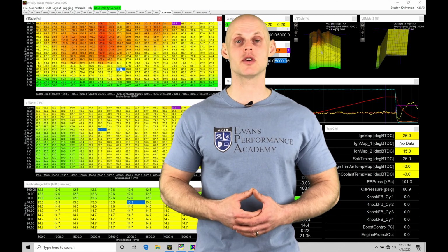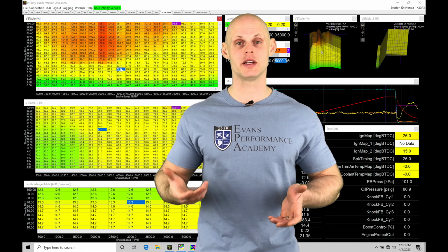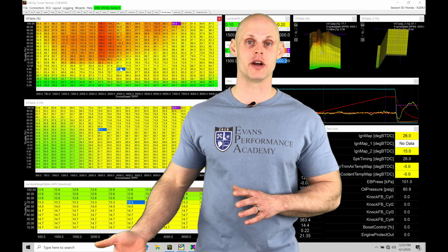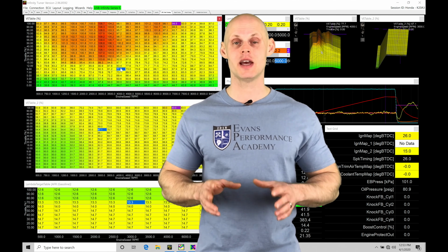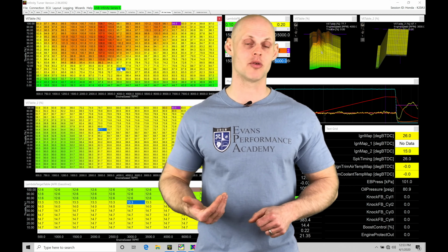In this video, we're going to start to work with our high cam fuel and ignition timing tuning. This is going to be our VTEC operation. So we have our VE table 1 for low cam, which we've already mapped out. The VE table 2 now is what we're going to be working on and calibrating in this video.